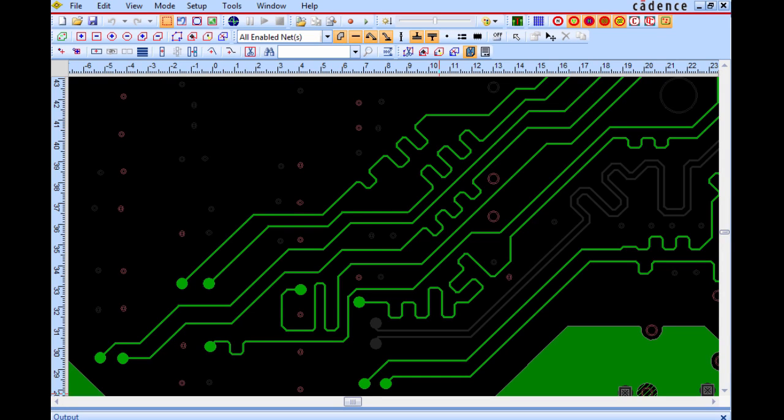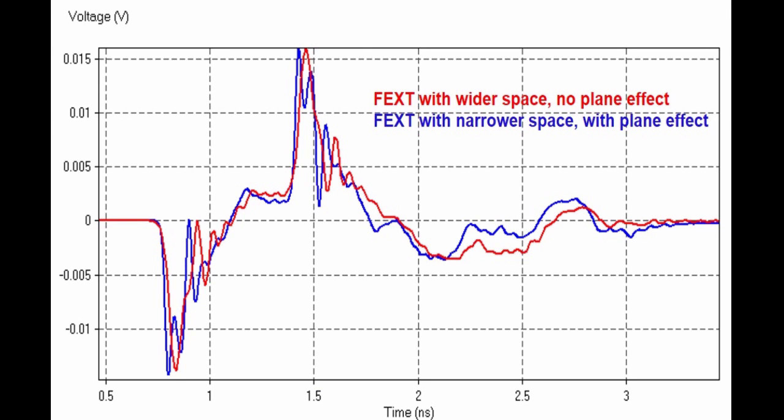One significant benefit of using SI matrix check is to pick up crosstalk impact through the plane canvas or between signal vias. For example, when higher crosstalk is observed on a signal in simulation without power noise, we can increase the distance separation to reduce it. With non-ideal power effect, this may not be true because of the extra crosstalk from signal via coupling through the plane canvas or plane bouncing.